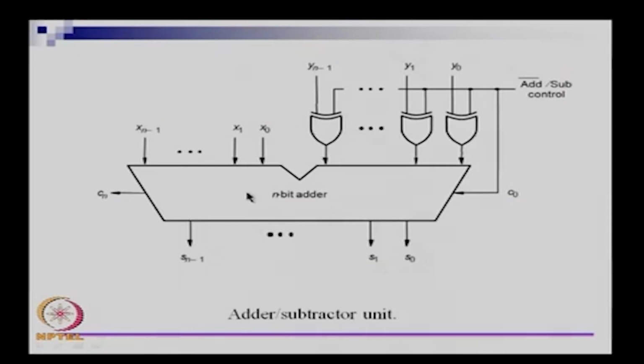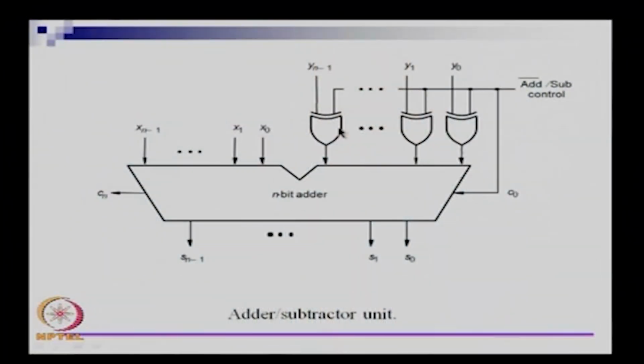In the next video I want to show how to design this black box. Once you know that black box, coming up with a 2's complement adder subtractor circuit is straightforward. So subtraction is not completely different, all it required is a bit of XOR gates. If I want an n bit subtractor, all I have to do is put n more XOR gates, that is all. It is as simple as that for 2's complement.